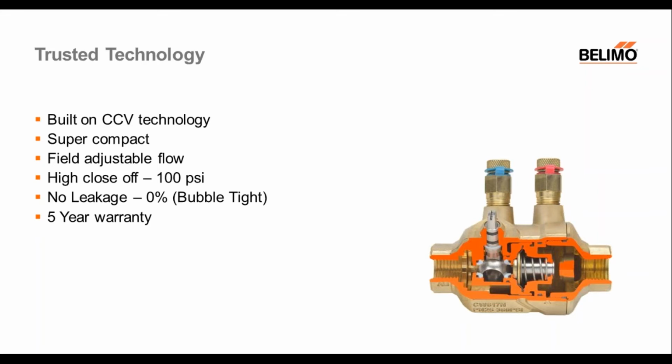We have a high close off of 100 PSI. We have zero leakage, and we have a 5-year warranty. So all these things combined in a compact zone valve.